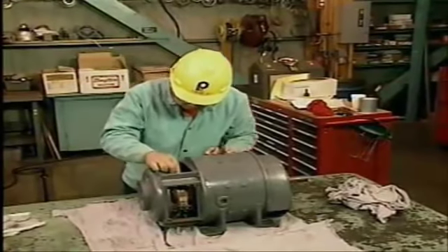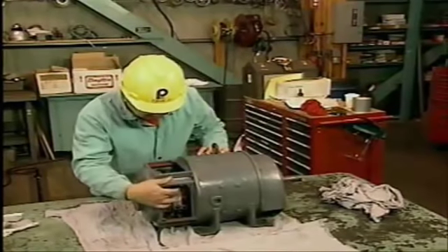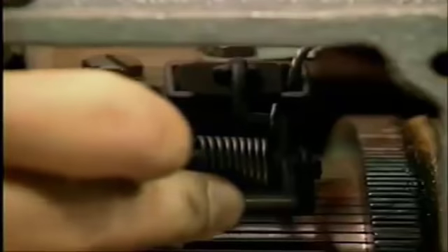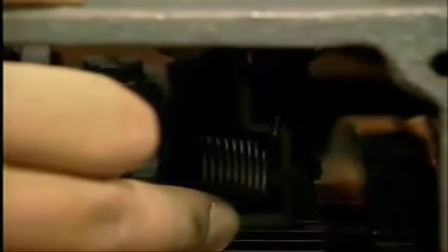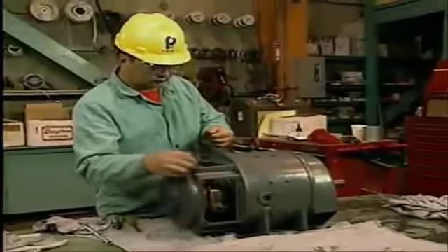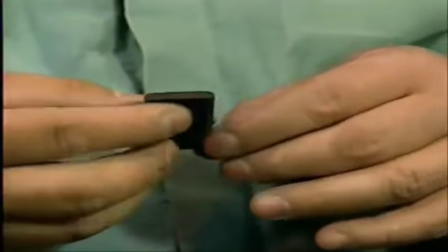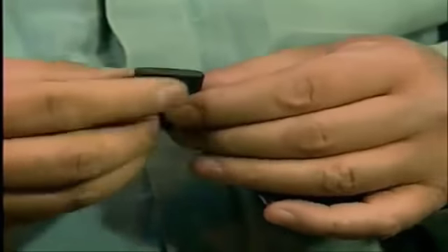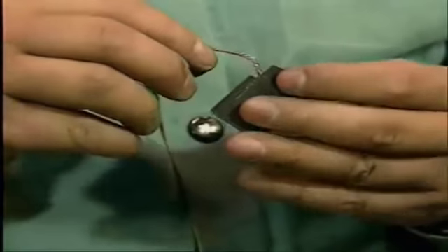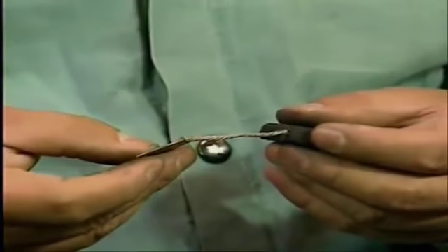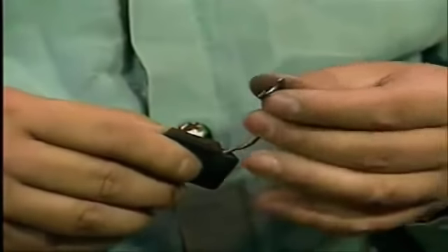After the interior of the motor has been thoroughly cleaned, the next step is to inspect the brushes and the brush rigging. The brush rigging includes the brush holders and the brush tensioning devices. The surfaces of the brushes should be checked for damage and wear. A brush that is damaged or worn down to 1/4 of its original length should be replaced. The brush pigtail should be securely fastened to the brush. The pigtail should be flexible, and it should not be frayed or discolored.